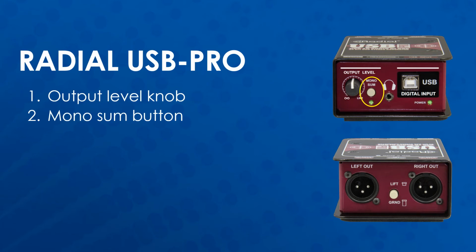Next to the output level knob is the mono sum button. It is recommended to have this button in the in position so that the mono sum LED turns on. This mixes the left and right signals internally and ensures that both left and right outputs are the same signal. This allows using only a single cable to output to a mixer and therefore takes up less input channels.